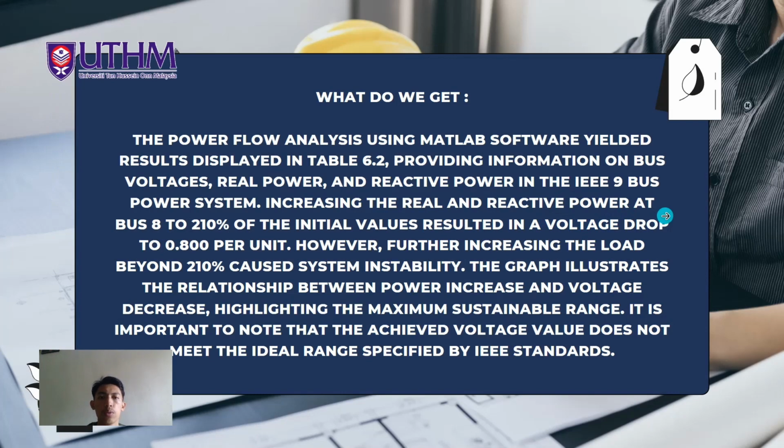What do we get? The power flow analysis using MATLAB software displayed in table 6.2 provides information on bus voltage. However, further increasing the load beyond 210% causes system instability. So the graph illustrates the relationship between power increase and voltage decrease.